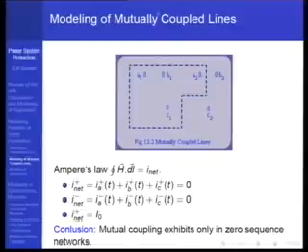But for zero sequence, what do you see? If these three currents are identical zero sequence currents I0, I0, I0, then the total MMF linking this path is 3I0, which is non-zero. So in zero sequence there is always a coupling. If two three-phase circuits are going close by to each other, there will be zero sequence coupling between them, but the coupling will not be there in the positive or negative sequence. That is another reason why you need to worry about this in short circuit analysis, but you will never worry about it in positive sequence analysis.